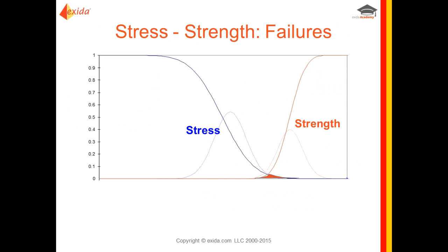If you take this flowchart, you can see that you have a specification of requirements, design, and implementation. You can break off. If you have a systematic fault, you will result in an improperly designed system. The system is not correct. You're going to have a failure. If you look at random failures, you might have a really well-designed system. The system is correct. Great. So you go down, but you still have a random failure. So the system is no longer correct. Both random and systematic faults or failures result in the system having a failure.